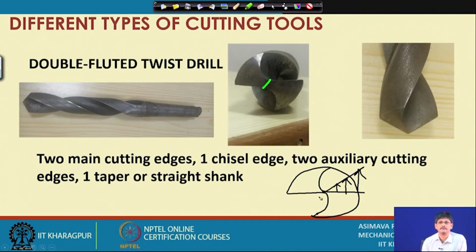But there is a problem here. The drill does not have any body in the middle to sustain all the stresses that it will have to endure. These two bodies would have had only a point contact, a line contact, which is very difficult to imagine. Therefore, in order to give it some body, we put the material here, so it has sufficient thickness, and here an edge forms.